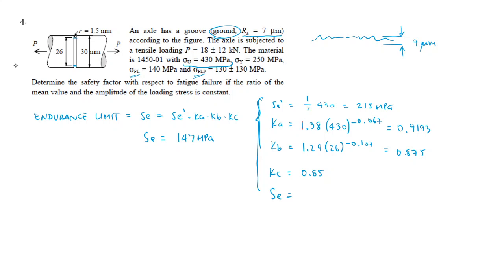Why am I going to use that? Because for my factor of safety, depending on the criterion that I use, let's go with Goodman so that it's the easiest for now. I'm going to have a sigma, in this case just the sigma, not the sigma prime, because it's only under tension, sigma M compared to SUT, and sigma A compared to the endurance limit.